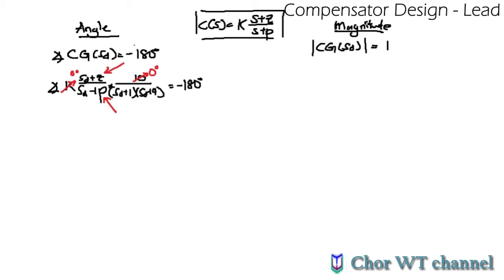In this case, to solve this, we will have to set one of the values. A normal approach that we are using here is for convenience. You can find a lot of other methods described in control theory, but for the demonstration here, we are just going to set the zero to be equal to one of the poles here, either -1 or -4.